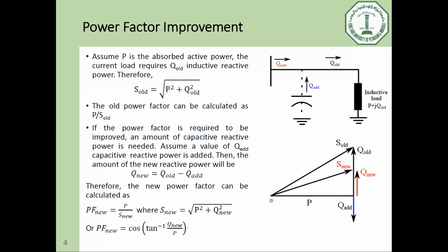If you already consume power with value P, but due to reactive power you consumed S value, this will increase the current absorbed from the supply. Because if you only consume active power, the value of S will be reduced down to P. Is it right, guys? The voltage is constant. So this means the current will be increased to achieve a high value of S because of the absorbed reactive power. So this means extra losses on the cables. Is it right?